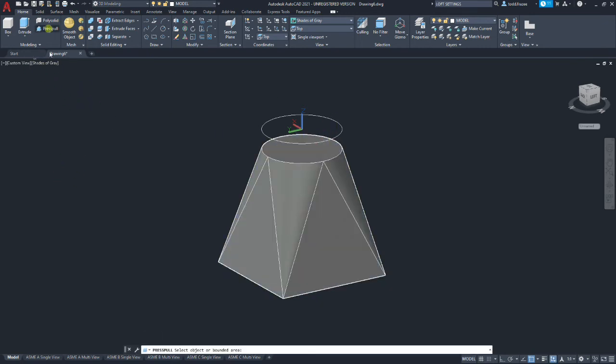And this time I'm going to use press pull. I haven't used that yet in this class for you guys, but it works pretty well. You can make holes with it and you can extend. It's a little bit faster than using the solid body. But you're going to select the top face, and it's going to allow us to push pull. And since we started with origin, we can just go ahead and select the origin, and it makes it the height of the distance we had there between the 2 circles.